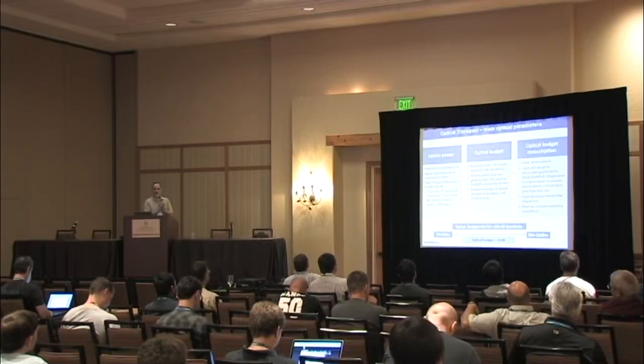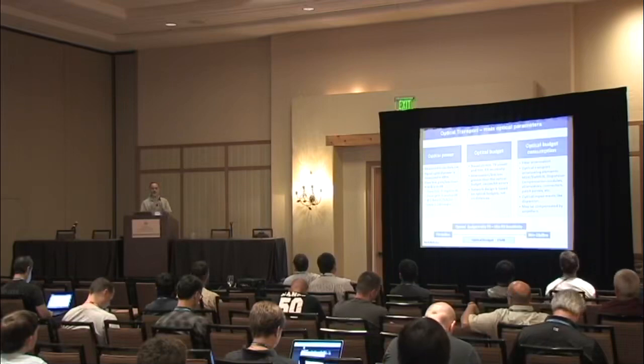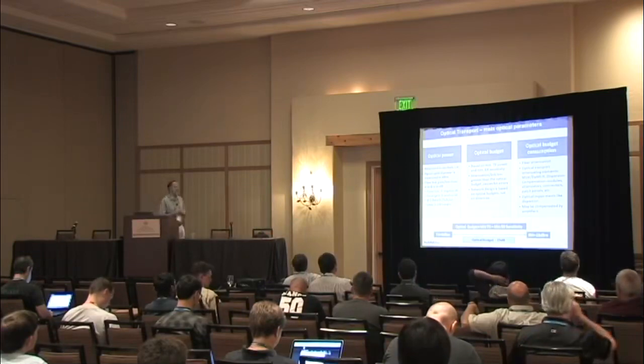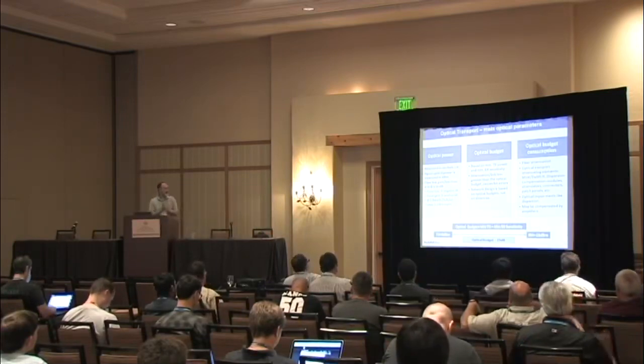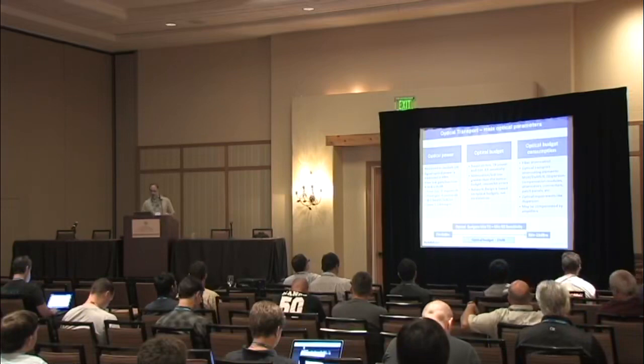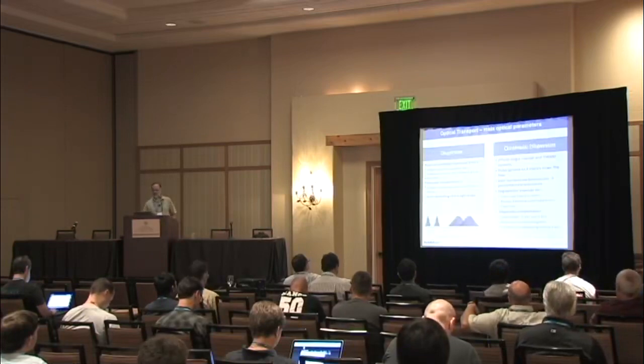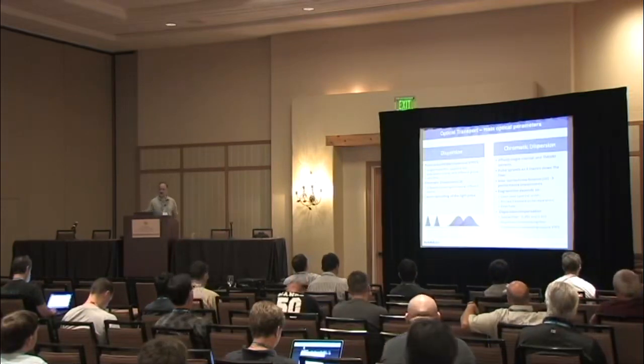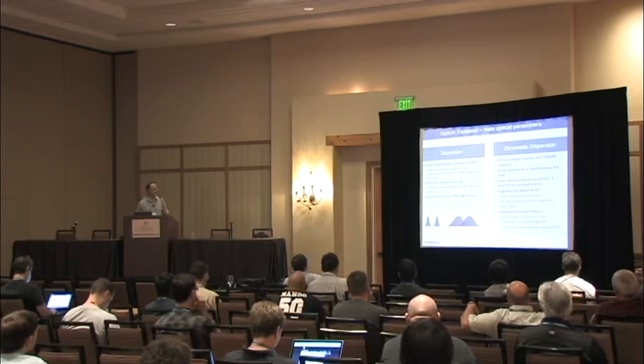Optical impairments like dispersion are translated, not sometimes, are translated into an optical attenuation or into a penalty. Luckily enough, the attenuation can be compensated by amplifiers. So let's talk a little bit about dispersion, caused by two phenomena in fiber.